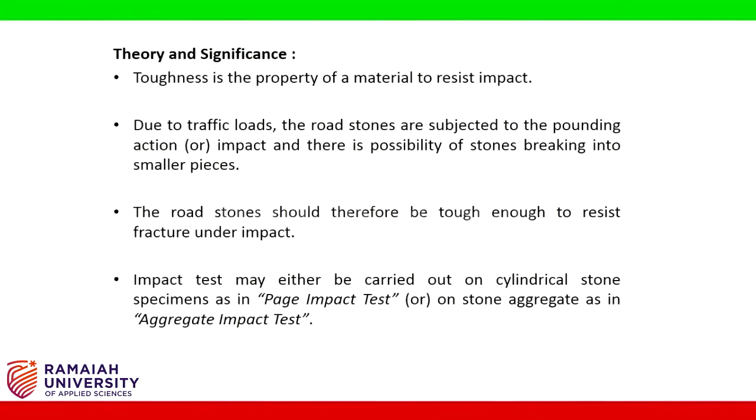Toughness is the property of a material to resist impact. Due to traffic loads, the road stones are subjected to the pounding action or impact, and there is a possibility of stones breaking into smaller pieces. The road stones should therefore be tough enough to resist fracture under impact.